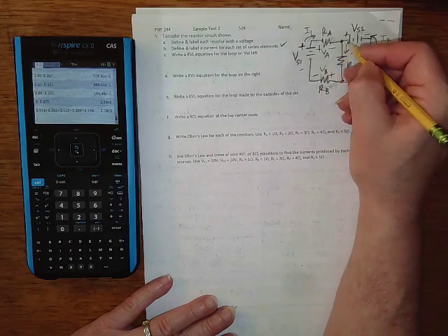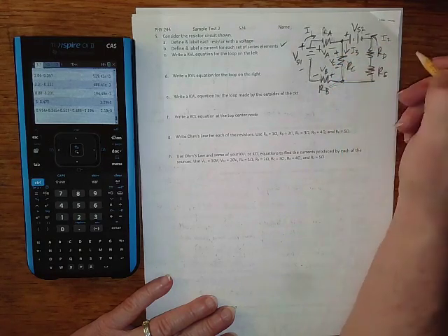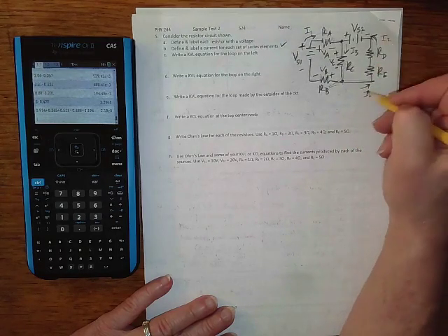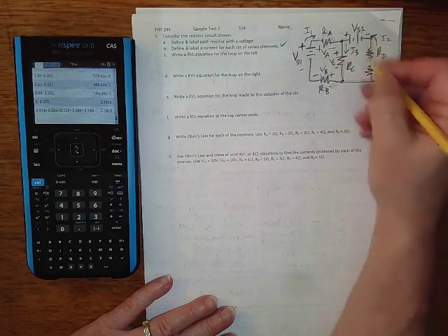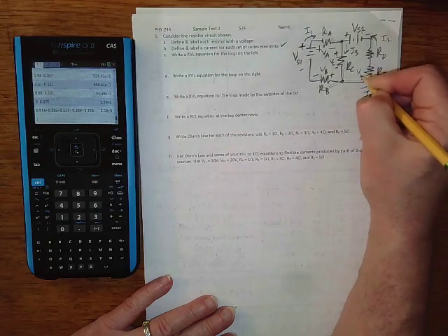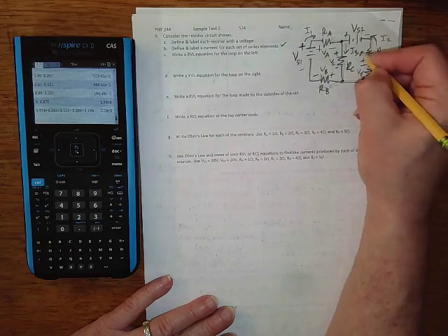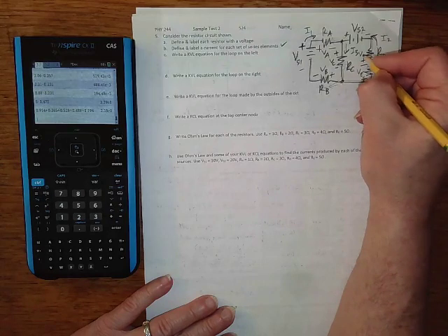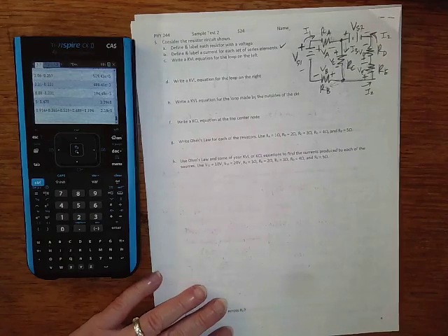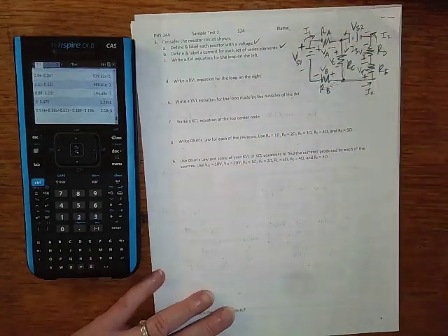VC, again, plus coming in: I3 is coming down, so the plus is the top, it comes in the top and goes out the bottom. Over here, I draw I2 again. I2 is going this way, so to come in the plus on RE, the plus has to be at the bottom. We'll call that VE. And then again here, same thing, it's coming in the bottom, so the bottom needs to be the plus, so VD is like so. All right, if we name it like that, we got nice positive sign convention. Our equations will make us happier when we write them. Okay.